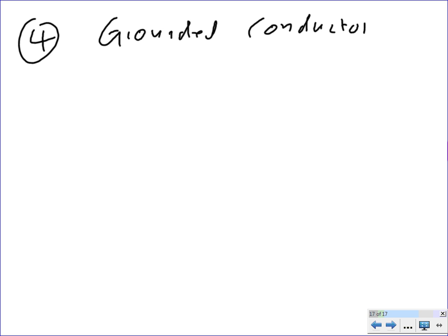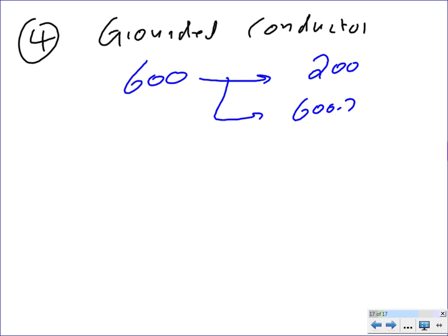So it's stranded. So we take the 600 amp. Here's what I would do. Disclaimer. I would take the first, remember the rule? The first 200 amp, leave him alone. Take 600 amp minus 200, multiply them by 0.7.